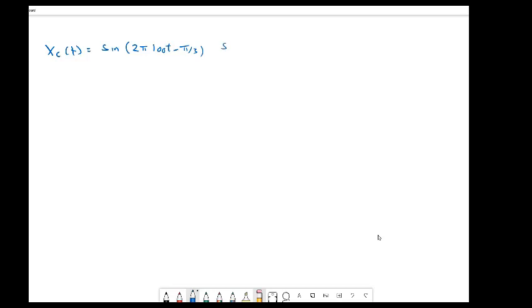And we sampled that at an F sample that was 150 hertz. And recognizing that the signal itself had an analog frequency of 100 hertz, we found that this particular signal did alias, but let's see if we can come to the same conclusion and determination in the discrete time domain.